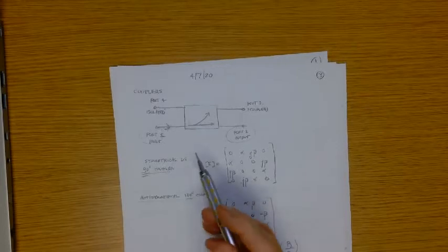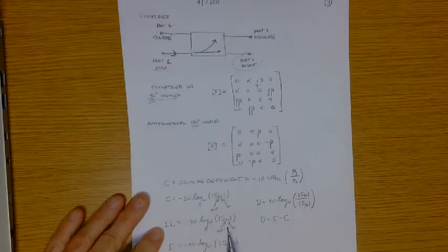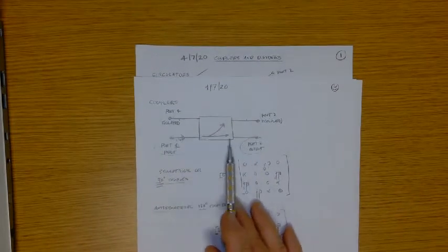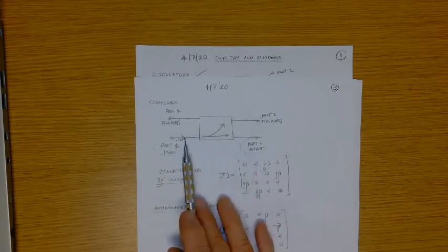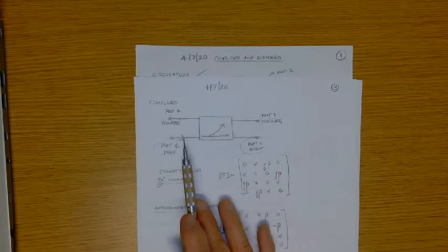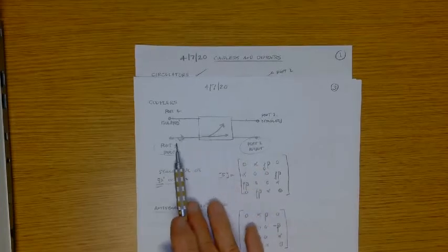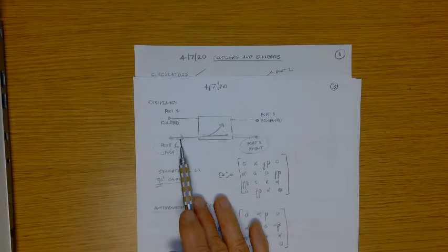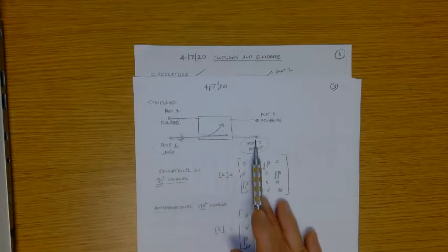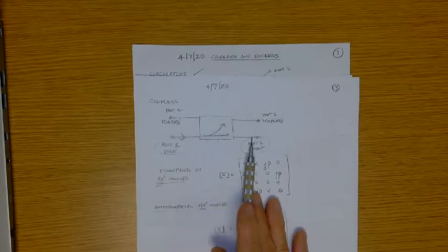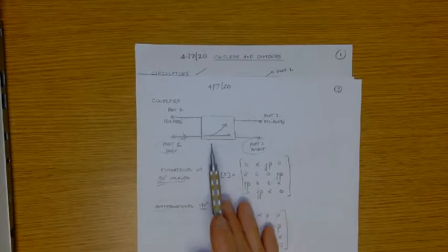Right, I'm putting in, remember how this goes, in port 1, out port 2. The device itself is going to absorb some power by virtue of its design. So when I input power in port 1, the power that comes out of port 2 will be less, right? And so when I insert this device between ports 1 and 2, I'm going to have some insertion loss.